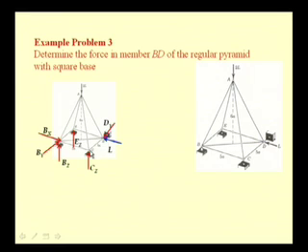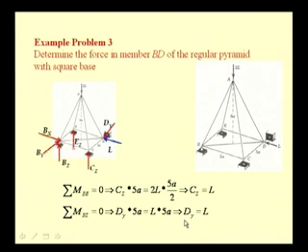So, we see that if we can determine the force in this member CD, then the problem can be solved, and in order to find the force in member CD we have to know this external reaction Cz. So, in order to determine the force in this member BD, it is sufficient to determine these two external reactions, that is dy and Cz. This can be determined by using the moment summation equation.